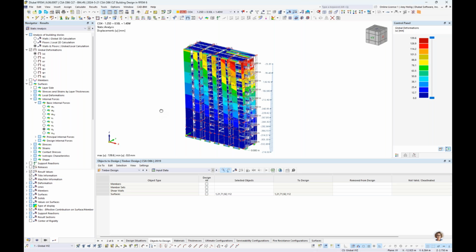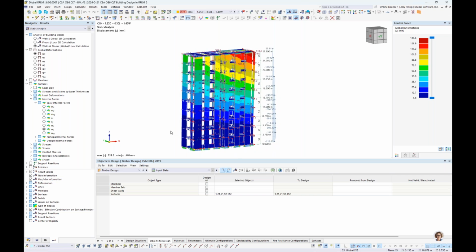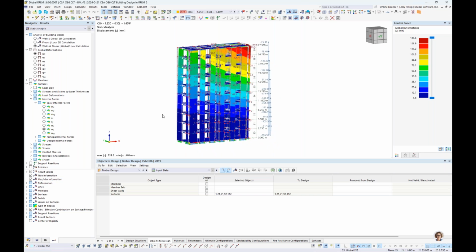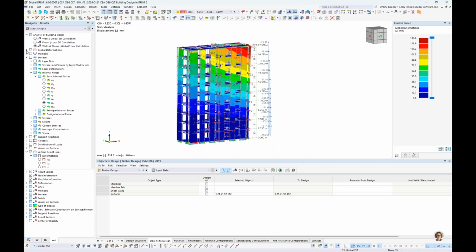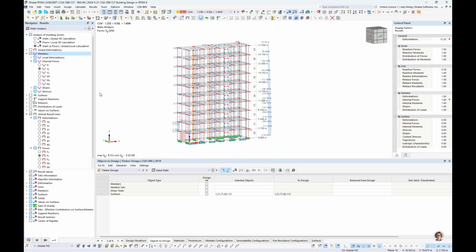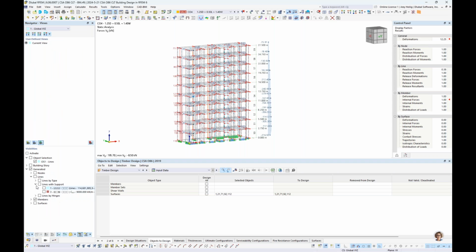Now, remember that we also carried out that shear wall calculation here. By defining those individual shear walls, the program will display this to us as standard members. So I'm going to activate here, I'll turn off the global deformations, we'll activate only the member forces. And what else I would like to display under my specific views is not necessarily all members, but members by type.